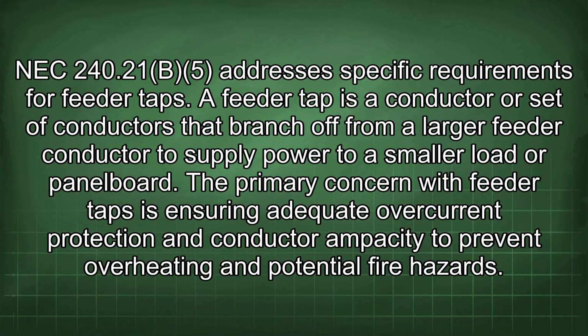NEC 240.21(B)(5) addresses specific requirements for feeder taps. A feeder tap is a conductor or set of conductors that branch off from a larger feeder conductor to supply power to a smaller load or panelboard.